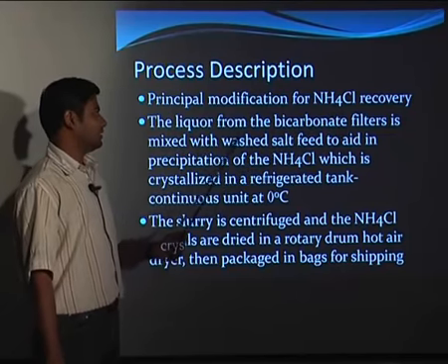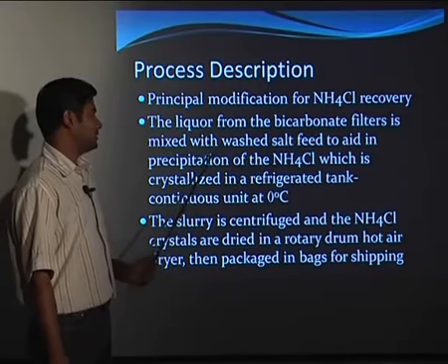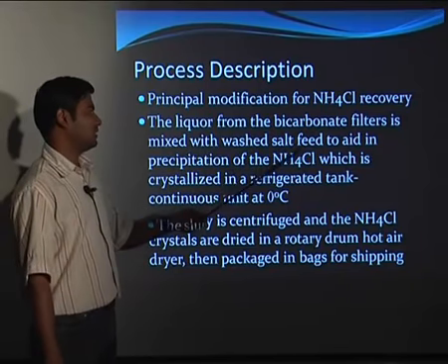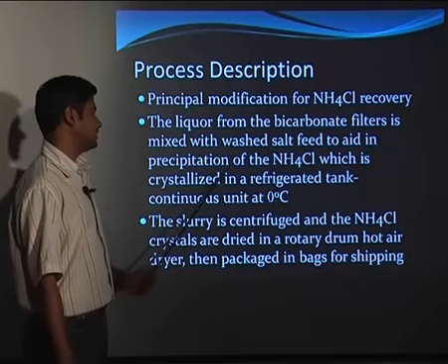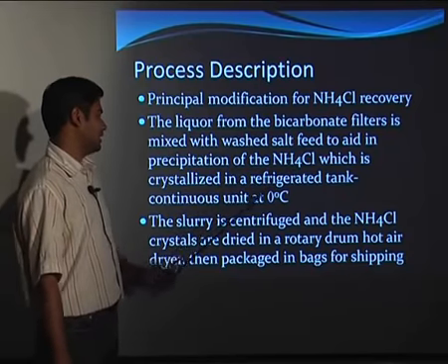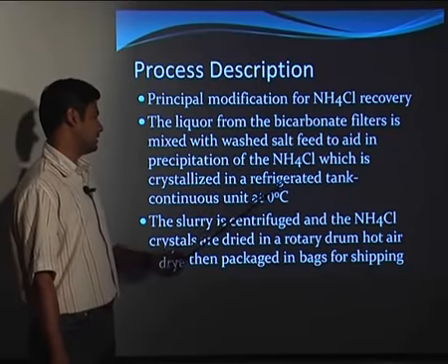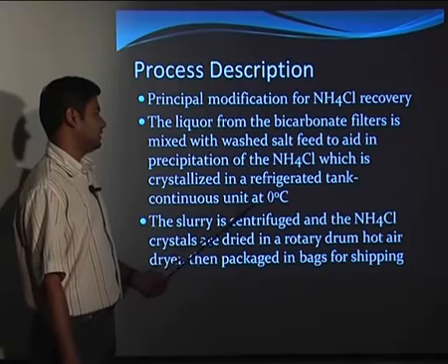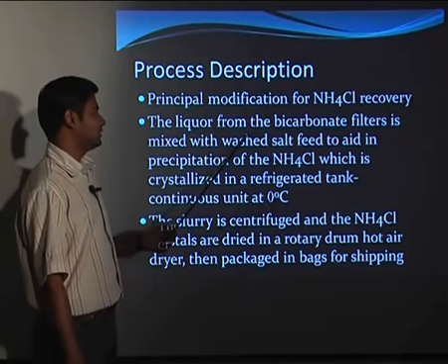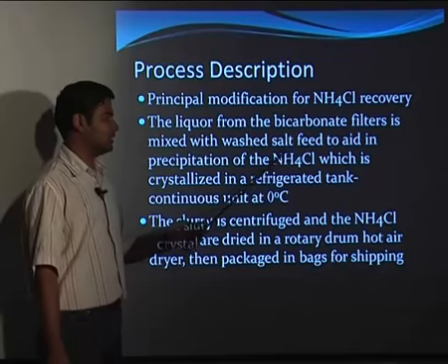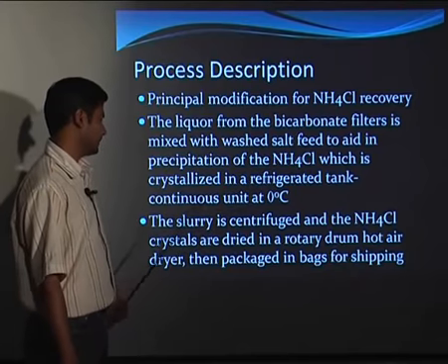The liquor from the bicarbonate filter is mixed with washed salt to aid in precipitation of the NH4Cl, which is crystallized in a refrigerated tank, continuous unit, at 0 degrees Celsius. So these are the things we do to get the NH4Cl as a co-product.